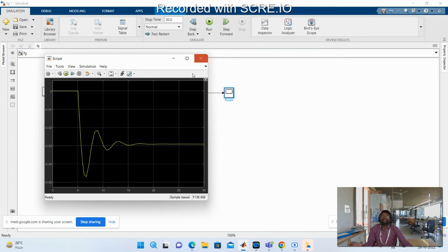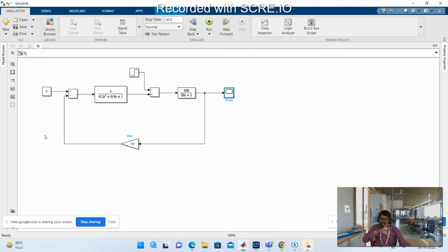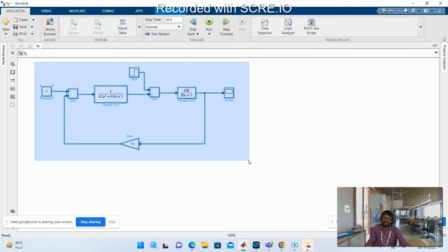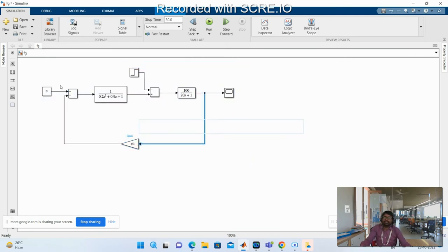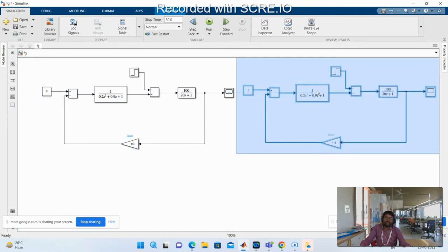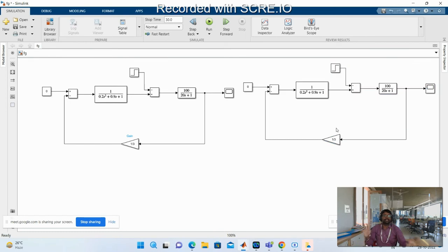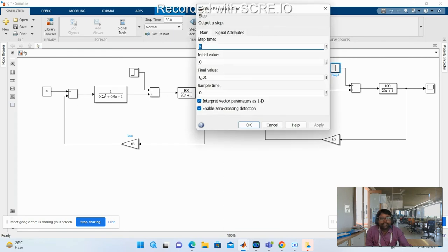Now, this is case 2, free governing operation. In case 2, sub case 1, delta P is positive, equal to 0.01. Now, what is sub case 2? We need to simulate the second sub case. So what changes do you have to incorporate in this block diagram? That's a question for you. Minus 0.01. Yes, in the step changing load, you have to keep minus